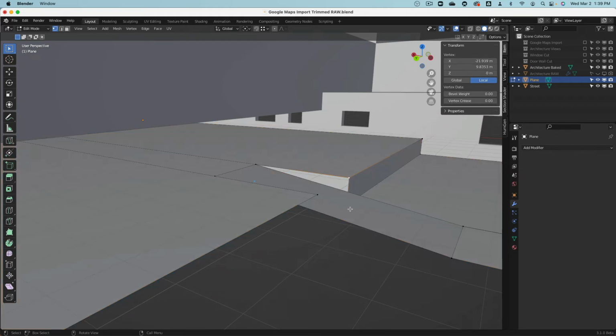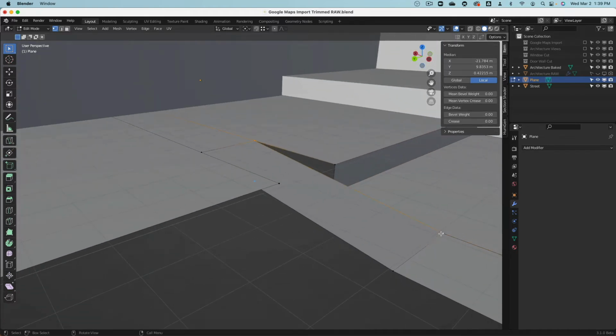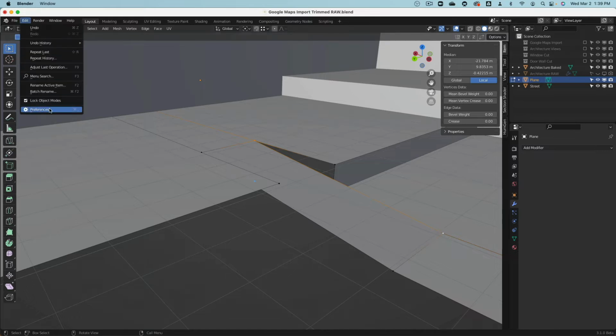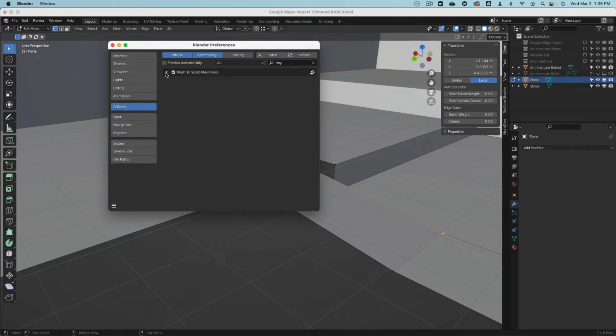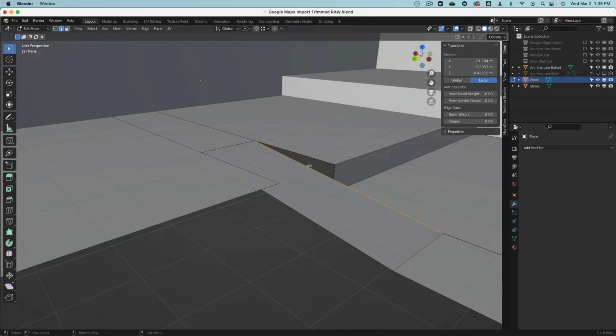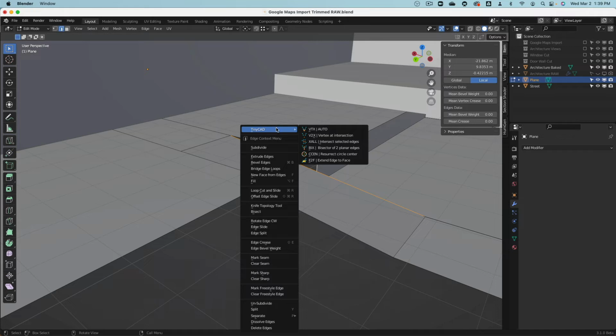Where this vertical line goes straight down, I would like to have a point where this connects. How can I find this? Blender has the tools built in. Go to the preferences, add-ons, then type in TinyCAD. Welcome to AutoCAD running in SketchUp. Blender, wrong program. Edge and edge selected. Right click, there it is. Intersect selected edges. Yeah.